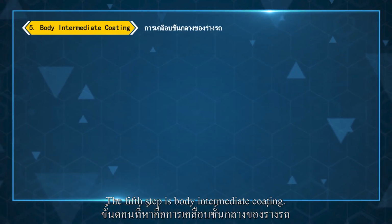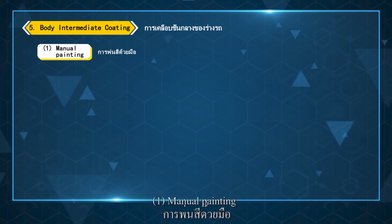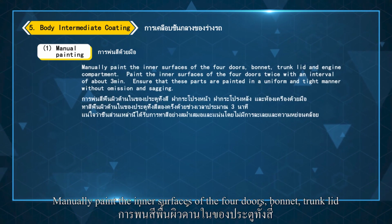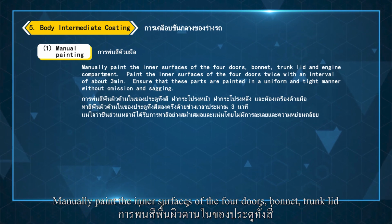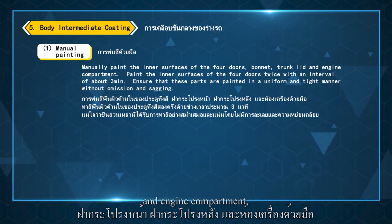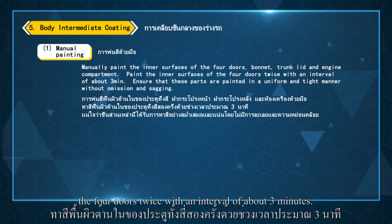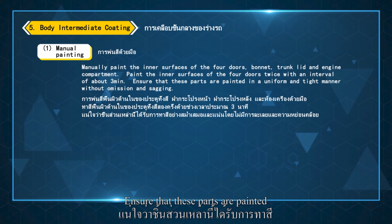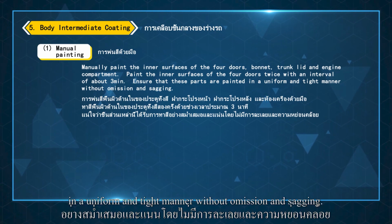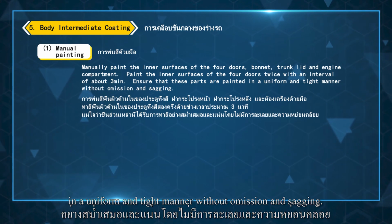The fifth step is body intermediate coating. 1. Manual painting. Manually paint the inner surfaces of the four doors, bonnet, trunk lid, and engine compartment. Paint the inner surfaces of the four doors twice with an interval of about 3 minutes. Ensure that these parts are painted in a uniform and tight manner without emission and sagging.